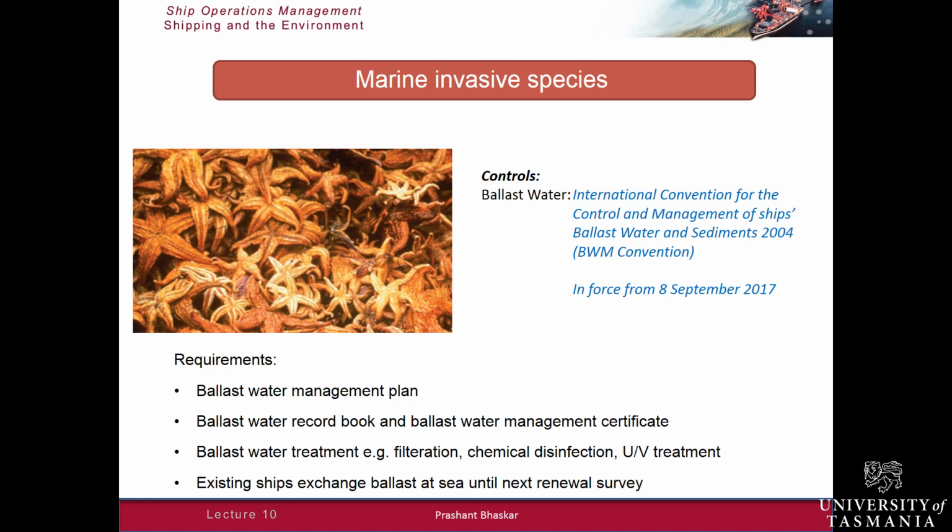So essentially, what the Ballast Water Management Convention requires is that every ship should have a ballast water management plan. It should have a ballast water record book and a ballast water management certificate. The record book should record every time the ballast is handled on the ship.